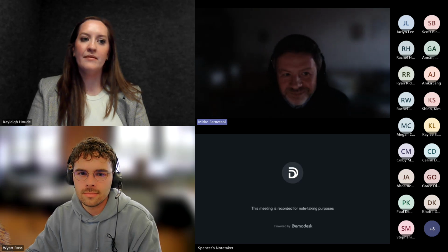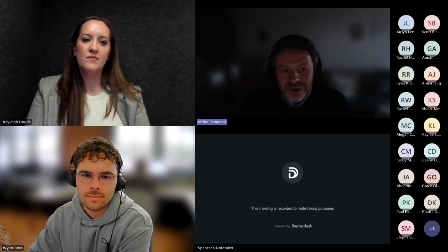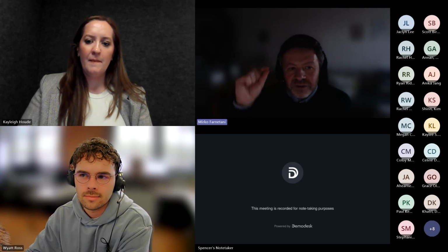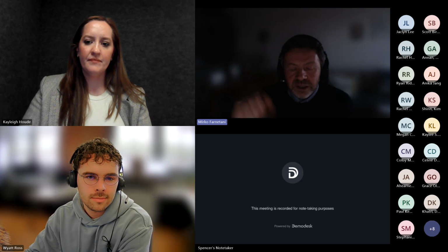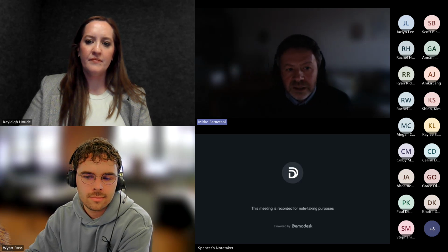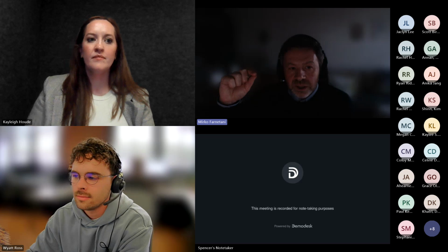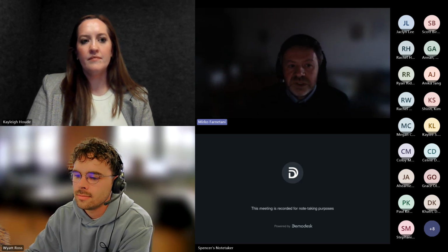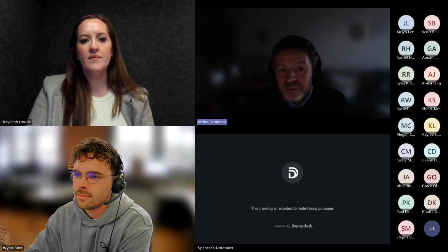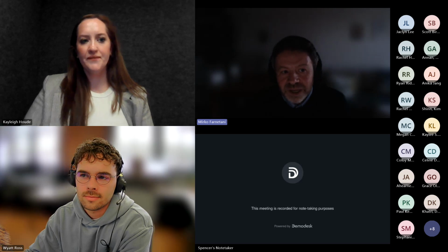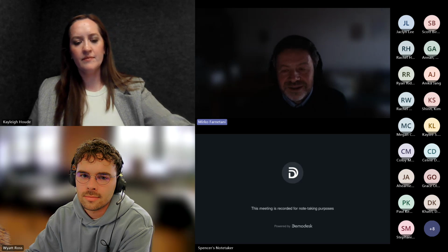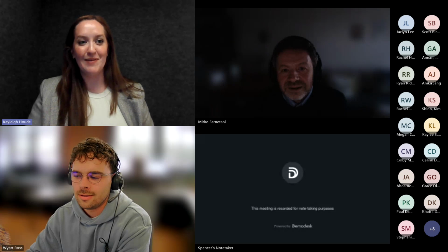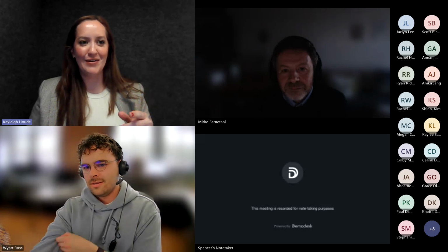Well, it depends on whether OneClick has this kind of conversion factor. If you select the EPD in OneClick, and go to unit, and click on the drop-down menu, you are able to see if the conversion is possible or not. If it's not possible, obviously, you have to calculate any conversion manually. I think we actually had to correct the EPD that was in OneClick because it was by watt peak and they had incorrectly scaled, right?